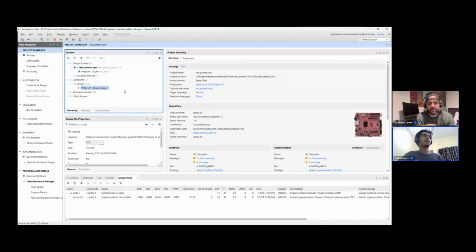So this constraints file comes into use in the implementation phase of the project, which defines the pins for the hardware peripherals which are interfaced. So onboard components are chosen and they are assigned certain pins. For example, in our case, these are the 4-bit LEDs, push buttons, and certain state selecting switches.